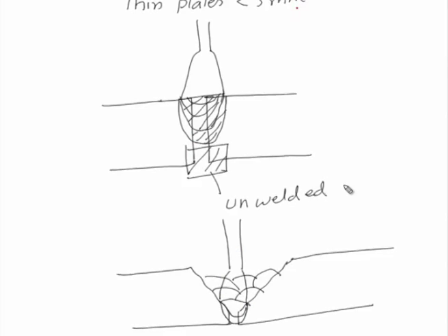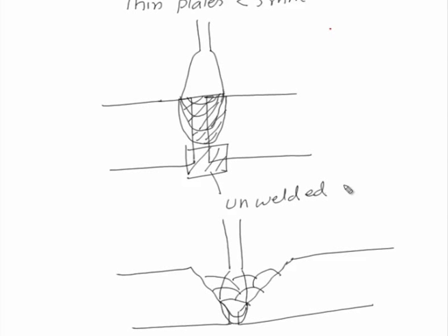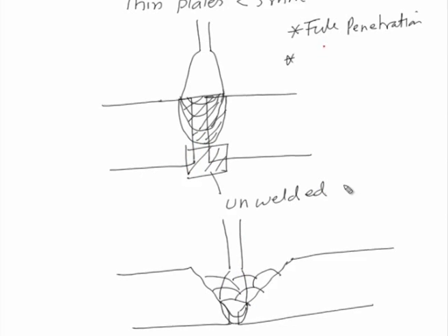So, in those situations where application of heat using the suitable heat source helps to melt the plates through the thickness, it results in the full penetration weld. And for those situations where the melting with the application of heat takes place only up to a certain depth of the plates, and thereafter development of the weld joint produces the partial penetration joint.